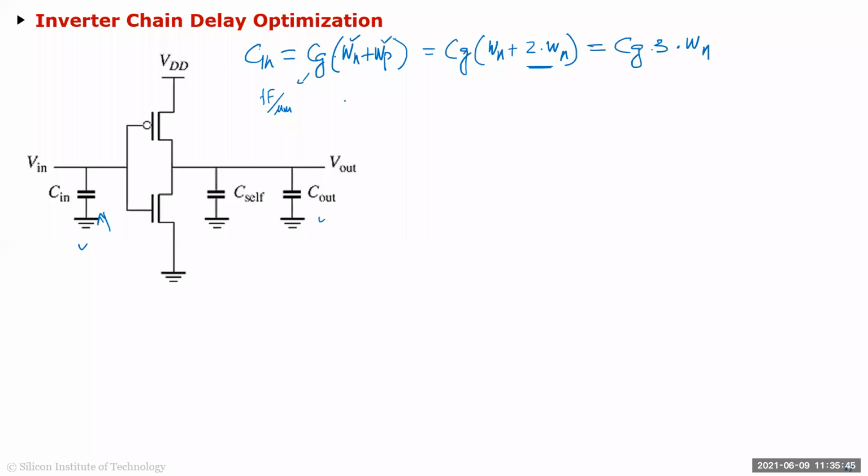Now, for the N, R effective N, we have already calculated it. So your effective Nmos is going to be the equivalent resistance we calculated times L over W, right? And if you have calculated the equivalent for, let's say, minimum length, then you basically take R equivalent over Wn, because you've already calculated for the minimum length.